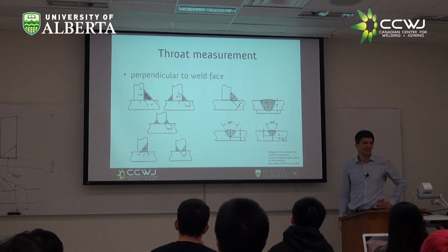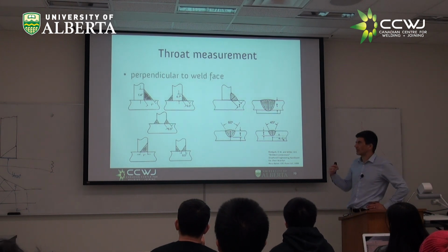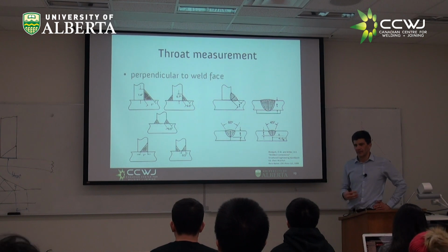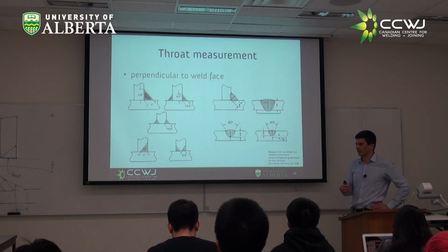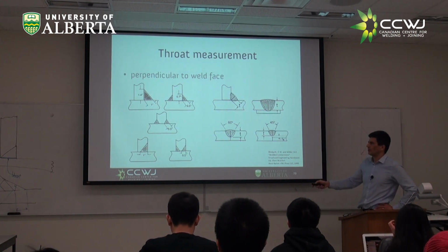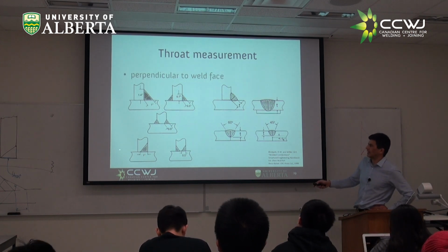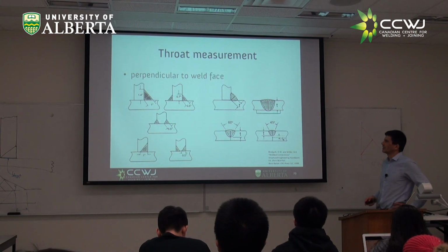What do you think? We know how to calculate the throat at least, right? And that's the number that goes into the formula, because these formulas assume that you break at the throat. So you don't go crazy about whether it is going to break a leg, unless we do overmatching. Okay.